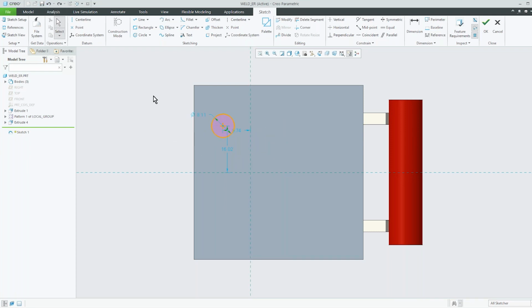So we just have our circle here, and I'll say, let's just make a line. Let's make a line that goes maybe up to this guy. And let's kind of move them back, maybe something like that. So now I can pick on our part here and say, let's mirror it about this line. So now we have them mirrored over there. And again, make it bigger, smaller.